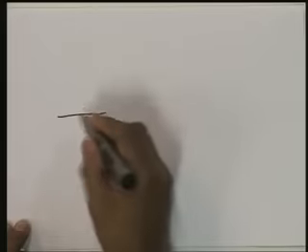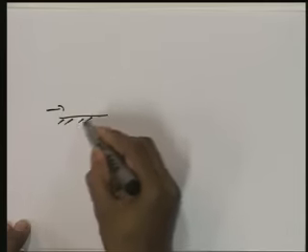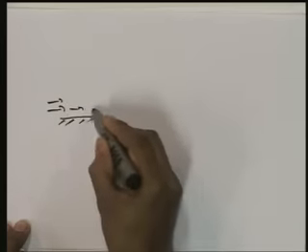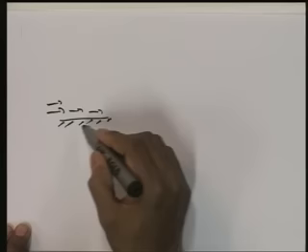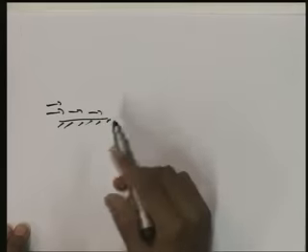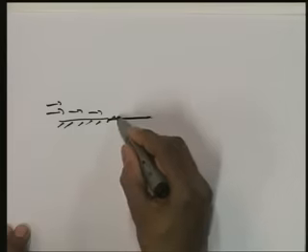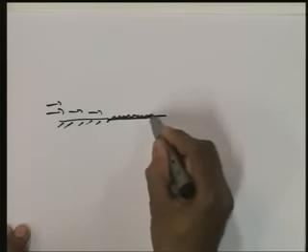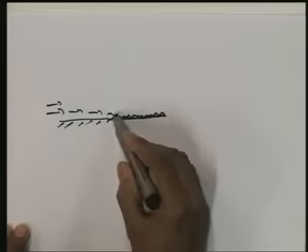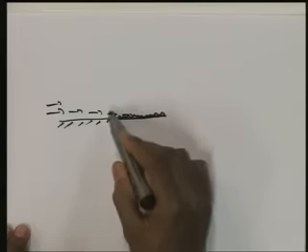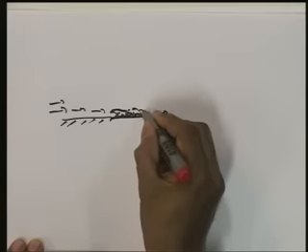Here I will just draw: the flow is coming here, and it is laminar. Here the bottom is smooth, and then if there is a small change here, that means the surface becomes rough, then due to the shearing effect the shear stress increases, and a small mixing starts here, and this laminar flow can become turbulent due to this reason.